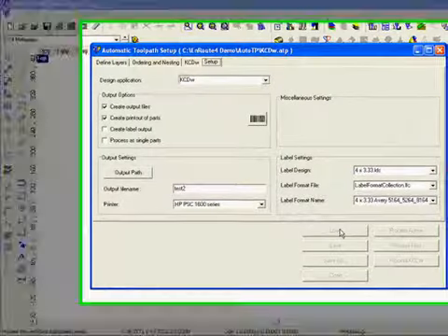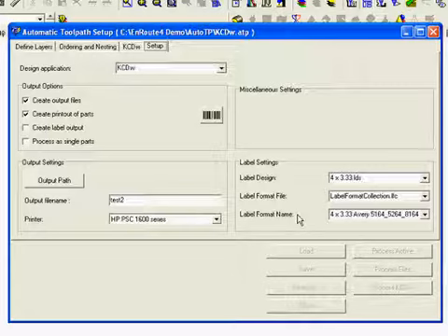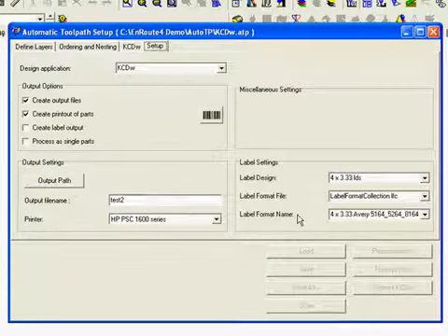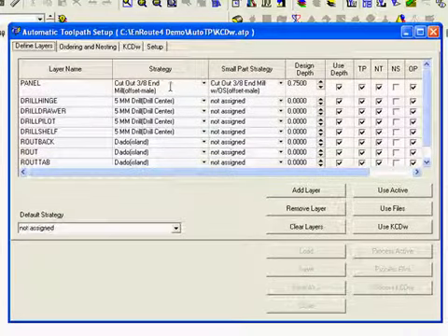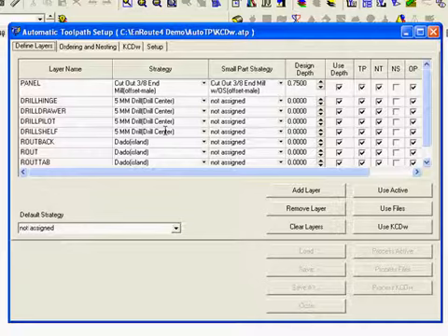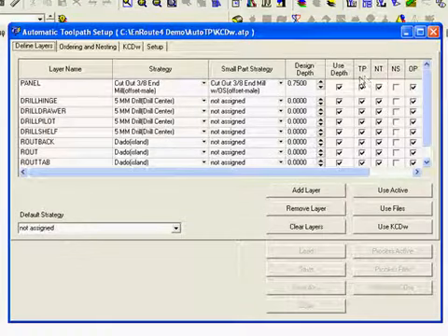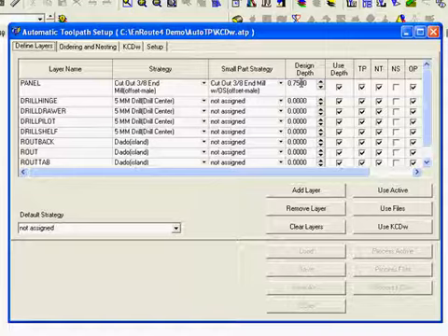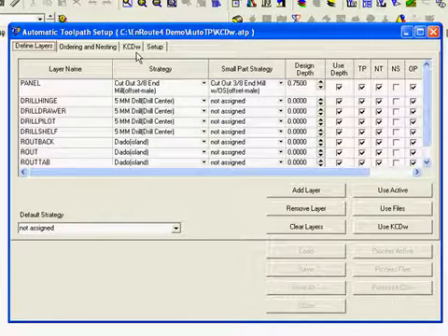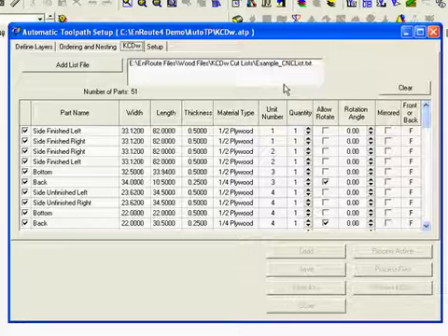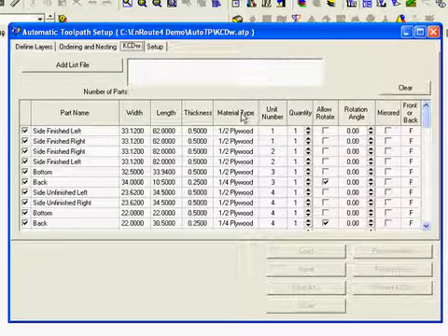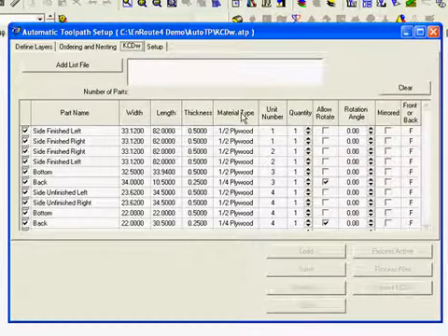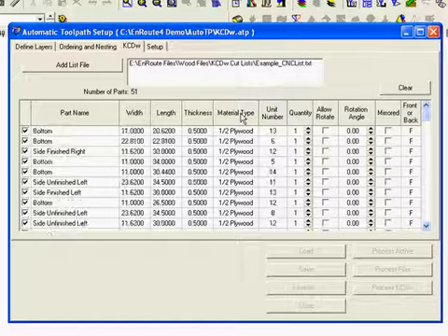So once again, the program here is reading each of these 60 or so DXF files, reading each of the layer names of the parts, and assigning the appropriate strategy. Some of them get cutouts, some get island fills for internal cutting. And then once this process is done, each part will be nested together as a single piece with all the other parts. And we're looking to put things that belong on the same material together. So the material type becomes important here. Enroute at the end of this process will let you know how many sheets you need of each material.